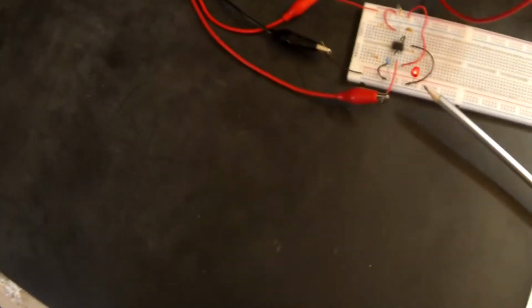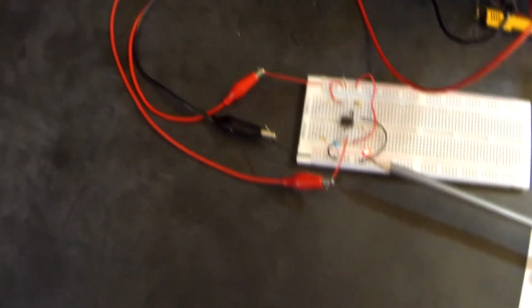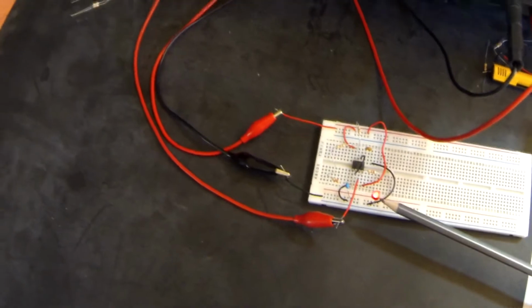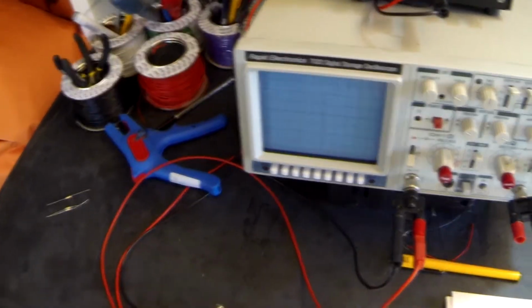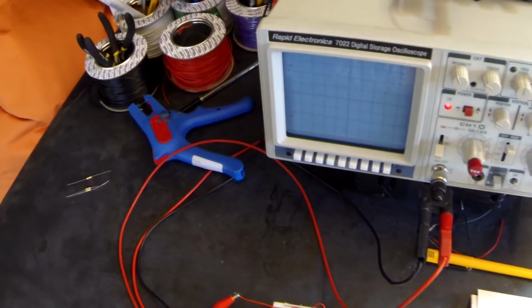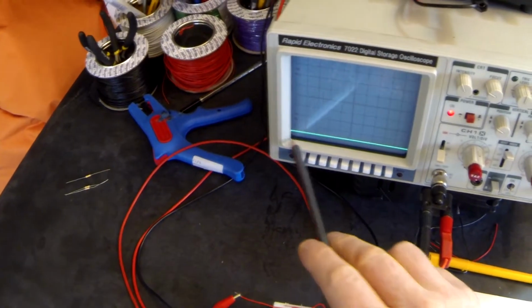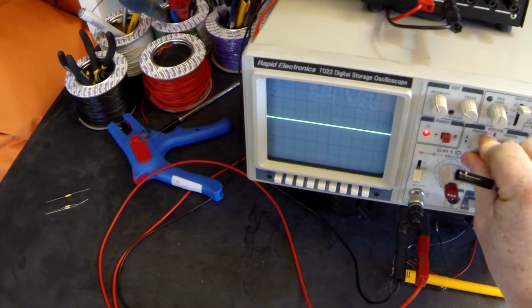So there we have our circuit. I've already turned it on. The LED is flashing, but once again, it's flashing far too quickly for us to see, so we need to use our oscilloscope. So I'm going to turn my oscilloscope on. Generally, the most difficult thing is getting a trace that we can see. You can see that the line is at the bottom, so the first thing to do is to put it onto ground and move the line up to the middle,